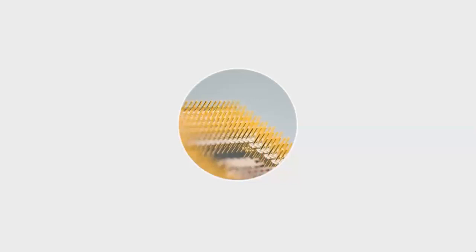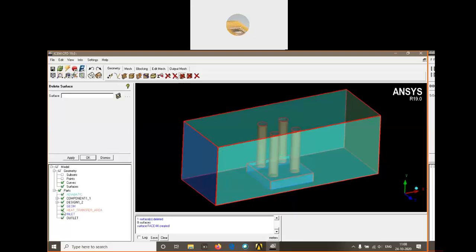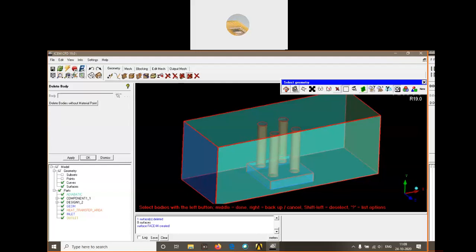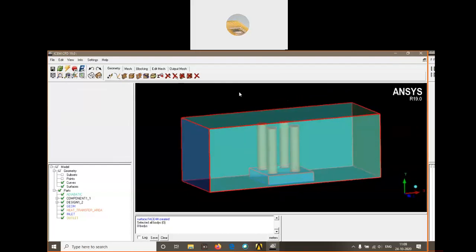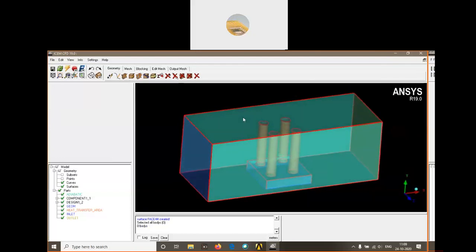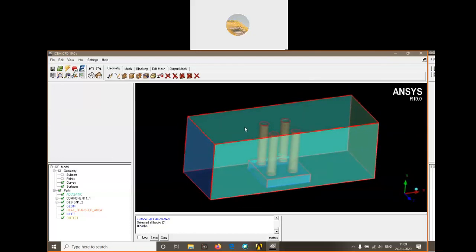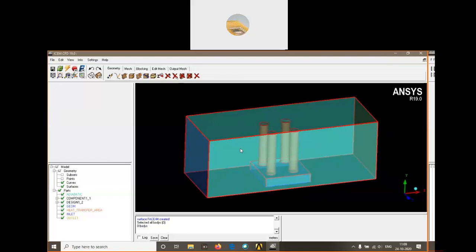Now I'm going to create a mesh, guys. See, in the bottom you will have inlet, outlet, heat transfer area, adiabatic area. Everything will be mentioned here. Now I'm going to do a thing. Fine. So this is just a check, some advanced level thing. You can learn it in future. Okay, fine. Now I'm going to define the boundary conditions, which is solid, which is fluid.